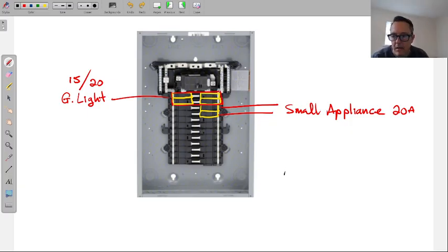All right, so in the house there will be again a closet, a room, a something where there'll be an outlet there, or two outlets there with a breaker in the panel representing that outlet. Trying to draw it a little bit straighter because I'm going to add another one. That circuit will be the laundry circuit.